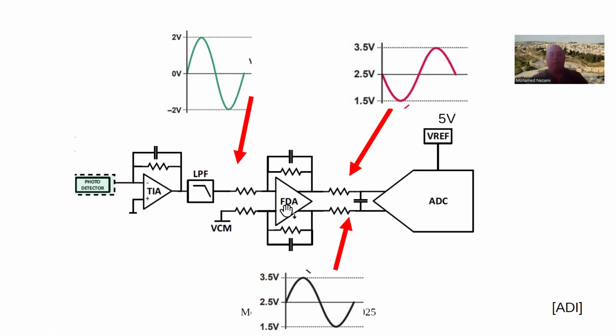Of course, the top half is exactly the same as the lower half. Talking about gigasample-per-second devices nowadays, there's a lot of effort on the layout to try to balance these things. Basically, for differential, if you have an input here, you split it into two parts equally, but out of phase. On the output, you get exactly the same two signals, except they are gained and DC offset. In this case, this is a common voltage, 2.5 volts. You see the same signal, but it has the gain, which is the ratio of this resistor to this resistor on both ends. This resistor had to be like 0.1% tolerance so that you preserve the common mode rejection ratio, because you really need symmetrical components, frequency response and values.